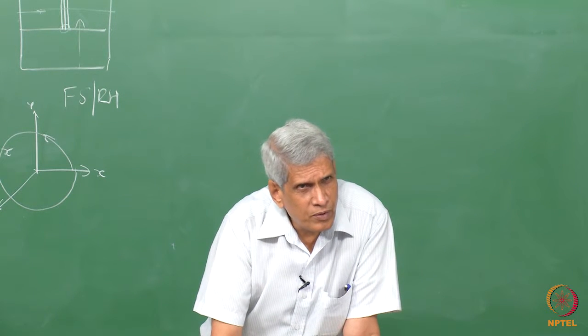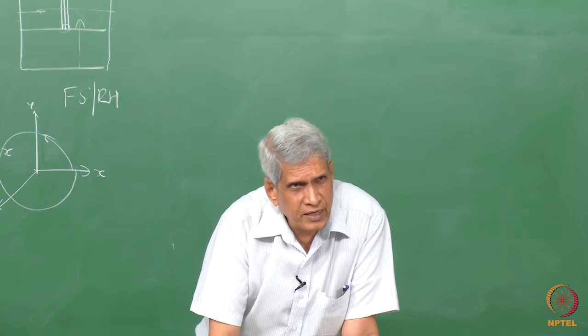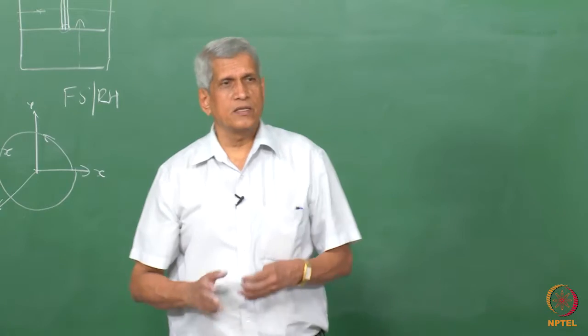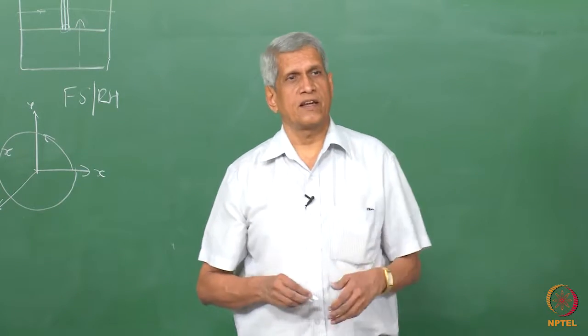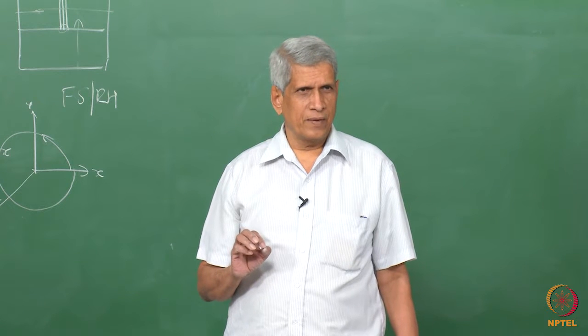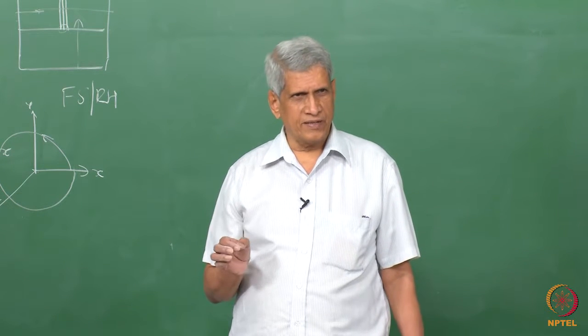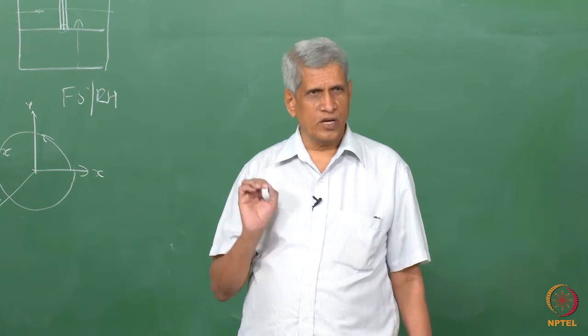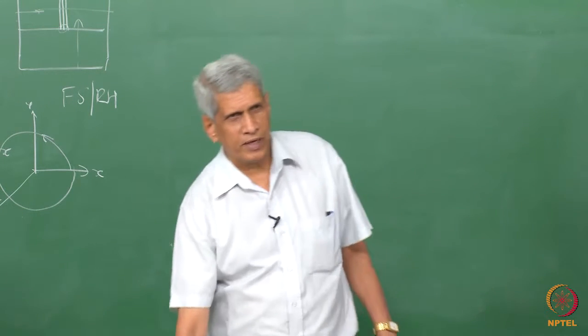When you point out the direction, that defines a vector. Generally in all the crystals this is going to be the lattice translation vector. Dislocations where the Burgers vector is a lattice translation vector, we call perfect dislocations.